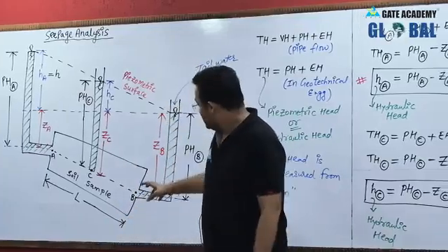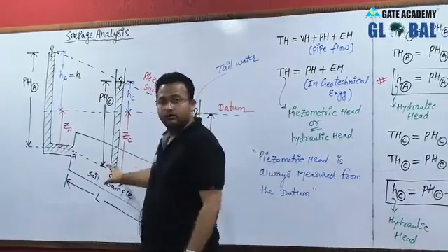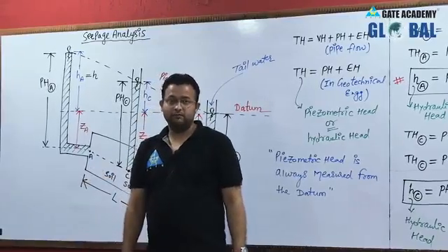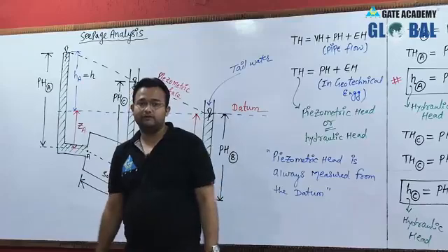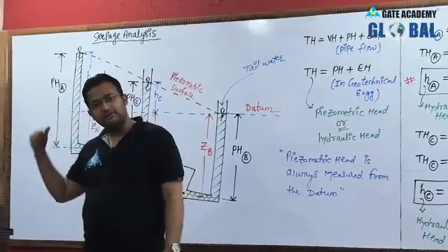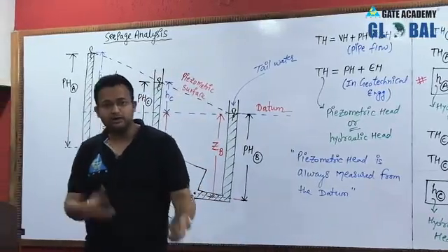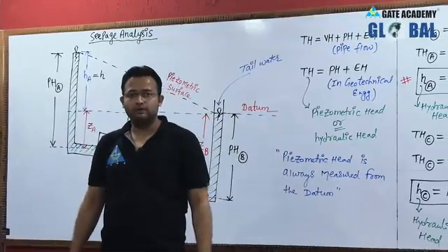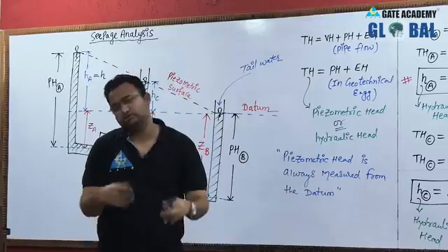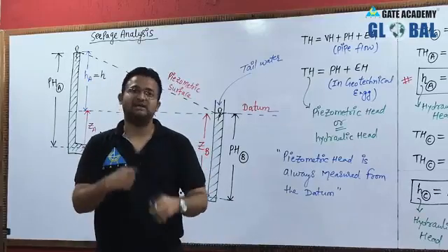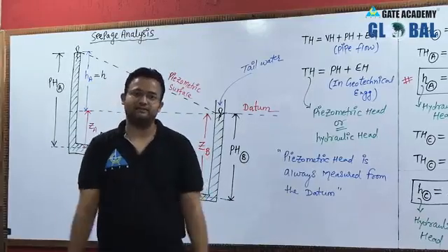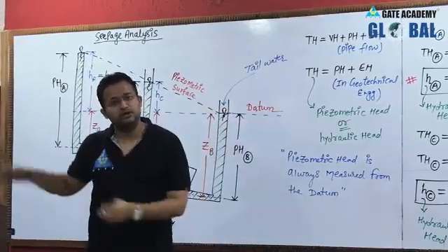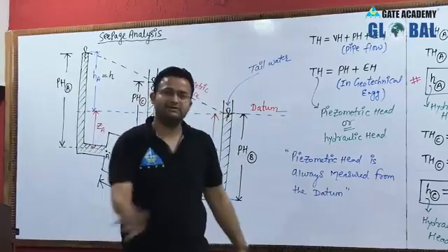So here soil should be stable, soil should have very good strength, so that because of this seepage pressure, soil solids should not flow with the water. Otherwise, if the soil is loose, having less stability, having less stiffness, then when the water comes, water is flowing from high head to low head, and with the water the soil will flow.